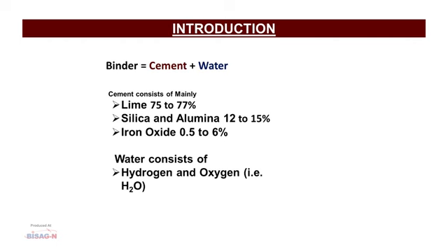The water cement ratio is the ratio of the weight of water to the weight of cement used in a concrete mix and has an important influence on the quality of concrete produced. A lower water cement ratio leads to higher strength and durability, but may make the mix more difficult to place. Placement difficulties can be resolved by using plasticizer or superplasticizer.